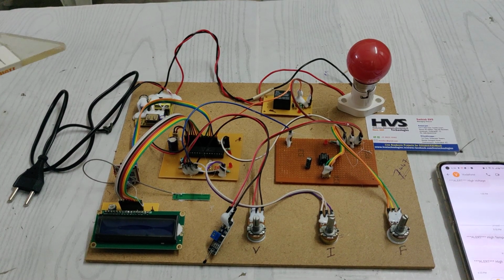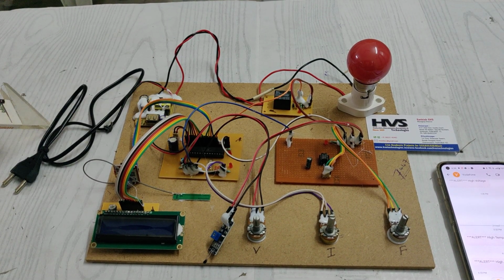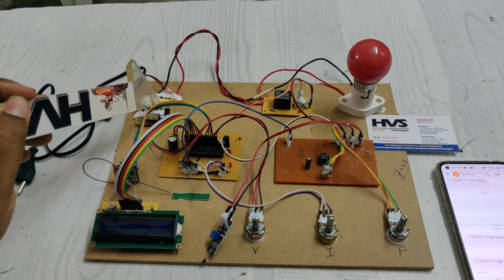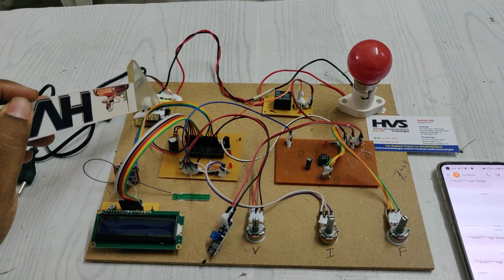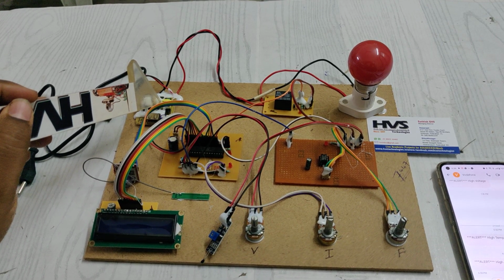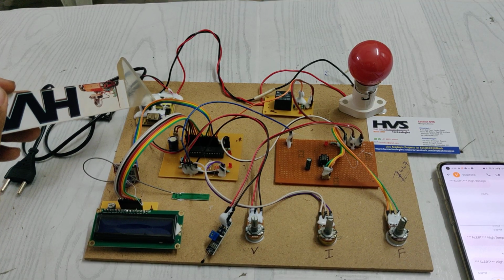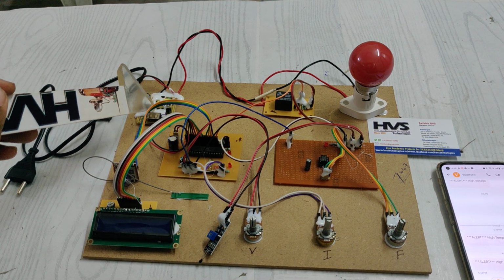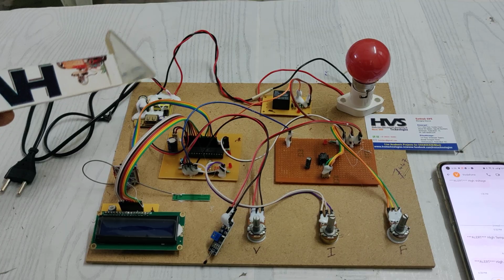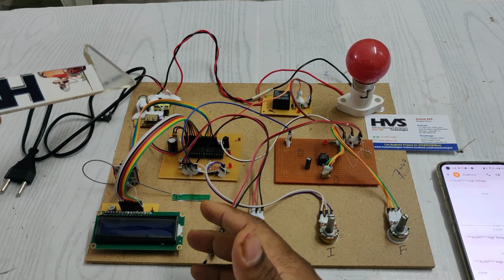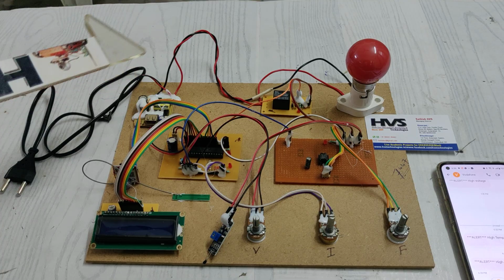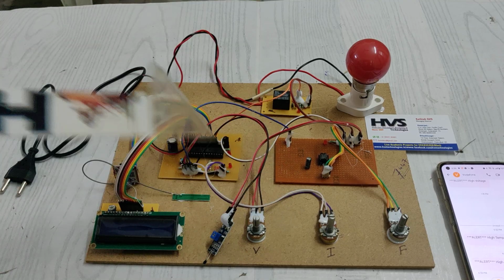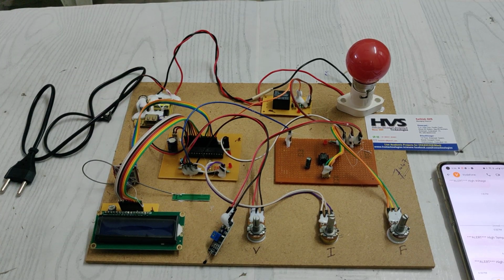To execute this, we provide the 230 volts AC input, which is the main input to this regulated power supply board, as it has 4 stages: transformation, rectification, filtration and regulation. Transformation steps down the 230 volts AC to 12 volts AC, and rectification converts the AC to pulsating DC. The filter makes that pulsating DC a pure DC voltage, and regulation regulates this 12 volts DC coming out from the filter to 5 volts DC. That 5 volts DC output is the main operating voltage for our whole electronic monitoring system. So let us check the demonstration.